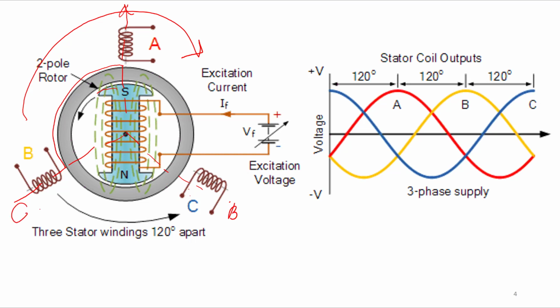So these 3 phase windings on the stator are actually distributed around the armature in the slots, and the axis of each of the coils for each phase are 120 degree apart from each other. Okay. Now the rotor having poles or having the field will rotate inside this armature, right? Now it will produce an EMF. So how will it produce in phase A?